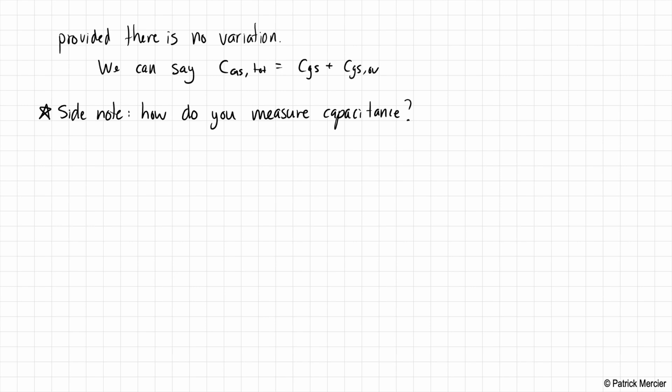Or let's say, perhaps more realistically, I give you a transistor model, and for whatever reason the model netlist is encrypted or something like this. You can't look it up, and so you need to figure out how to simulate this device and figure out how much capacitance there is. Okay, so we don't have necessarily just a capacitance meter or a capacitance measure function in HSPICE, for example, and so you typically have to construct your own ways to measure capacitance.